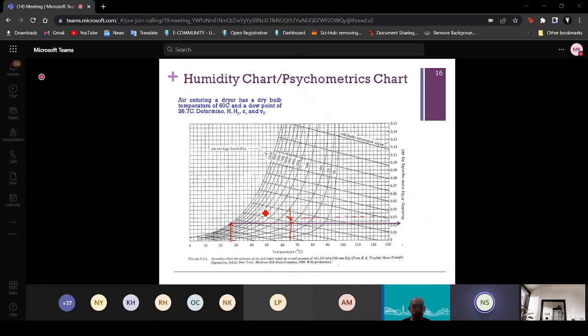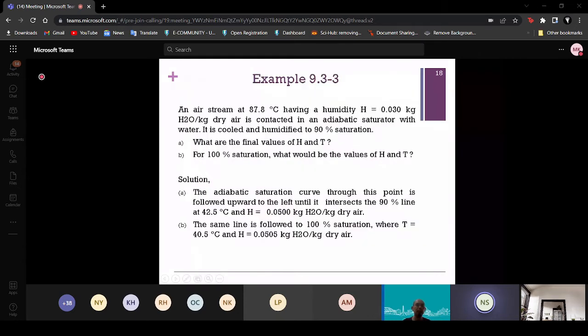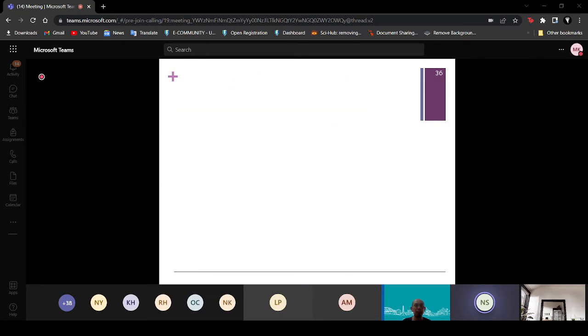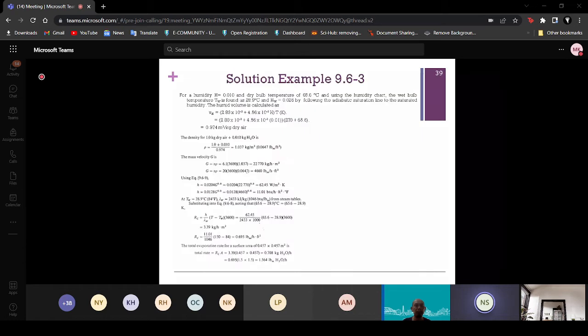So this is the intercept. So to get the wet bulb, take the closest one, take a ruler, go up, draw a line to the end. So you get the T wet bulb around 30 something. Okay, so now we know something. Put it in here. So you take, oh sorry, 0.01. Okay, sorry, I thought it was 0.03. You're all quiet, I think you're all sleeping. Okay, 0.01, so you will get T wet bulb 28.9. You can find it. So you have got the T wet bulb.